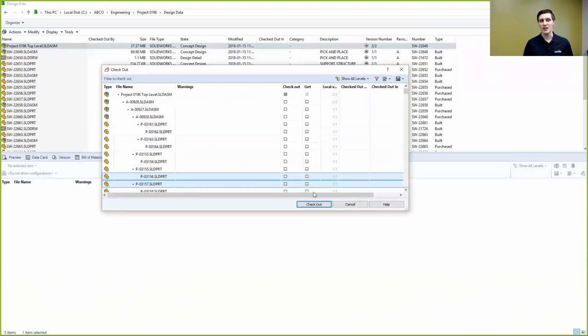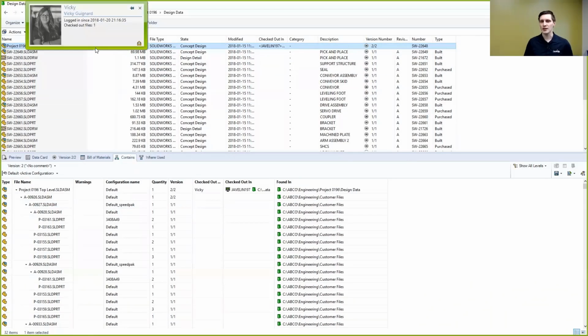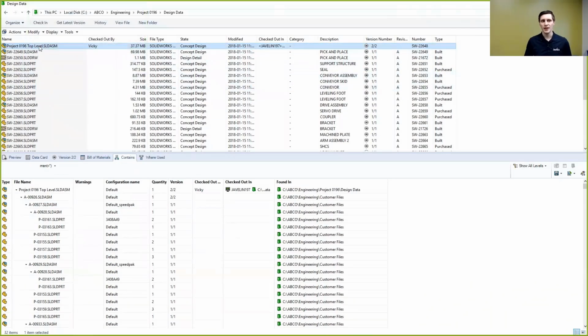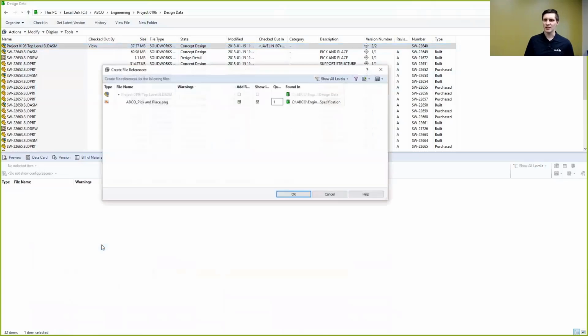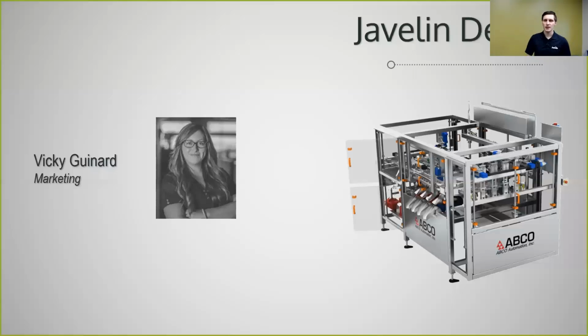And the change that we're going to make is we're going to paste that Visualize rendering directly onto that assembly file. So it sounds kind of funny because we're pasting an image onto a file, but by doing it this way, that rendering is going to follow this file around no matter where it goes. So we're always going to have easy access to that rendering. And again, it's going to easily connect our digital thread together, which maintains all of our information in one place. Easy to find.